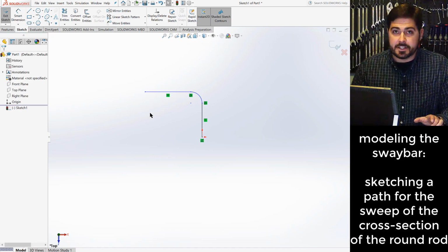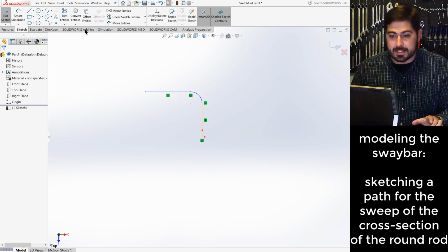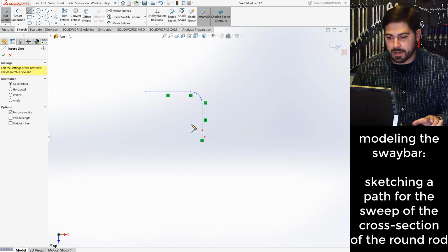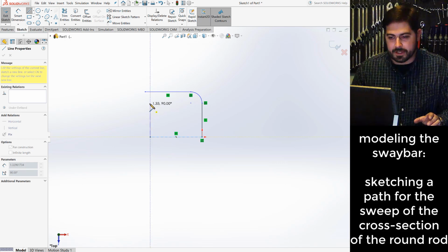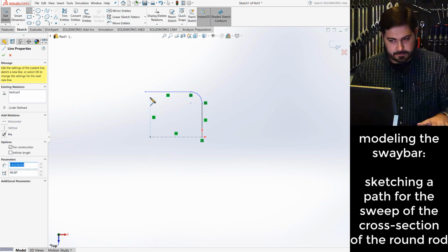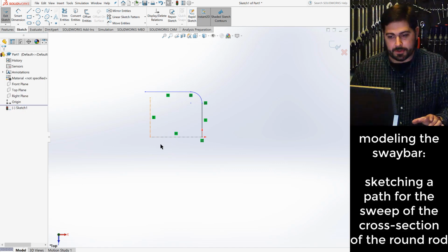All right, the next thing I want to do is make sure that this leg over here on this side is the right length. And so I'm going to do that by putting a center line in here. Actually, I'm going to do this by doing two center lines. One center line is going to be over like that, and the other center line is going to be up like this. And right now I haven't specified the lengths of either of those.